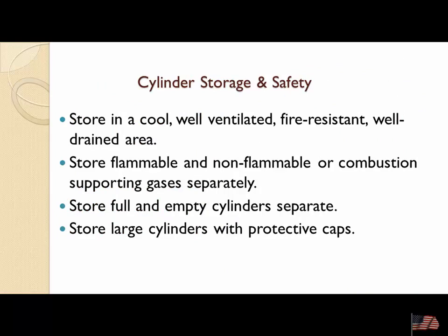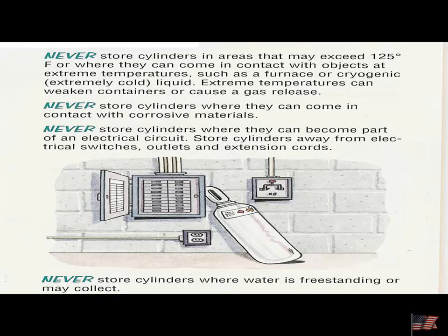So storage of cylinders is regulated again by the NFPA. They want to store them in a cool, well-ventilated, fire-resistant area. We store flammable, non-flammable, or combustible supporting gases separately. So we never store oxygen with something that is flammable. We store full and empty cylinders separately, so they're segregated. And we store large cylinders with protective caps that actually are screwed on.